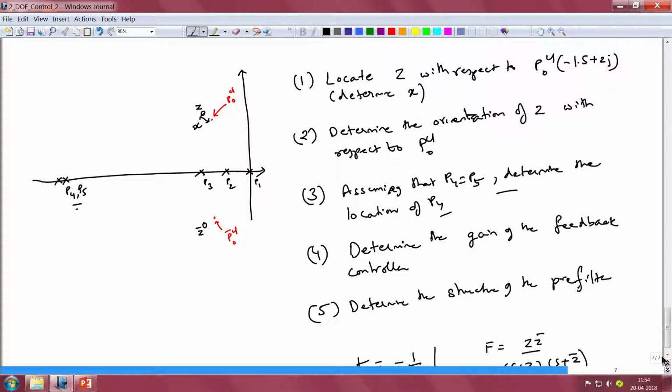So, we have to place the two zeros very close to these poles, and these zeros have the effect of pinning these closed loop poles and arresting the variation of the closed loop pole due to the changes in the plant's parameters. But because the controller has two zeros, it also needs to have two poles. So, we have to choose to place the poles at some distance, and we assume that they are placed quite some distance away from the origin.